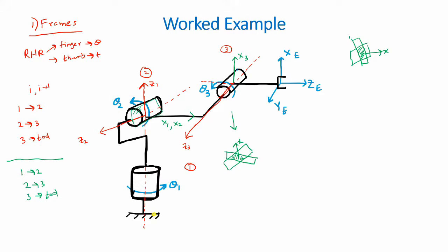Right, so this marking here shows that this is the base frame, so we can assume the origin of the base frame would be at this point. We will assign the base frame arbitrarily, but we will do so to closely match the first frame. So Z0 would be along here, and X0 would be in this direction.